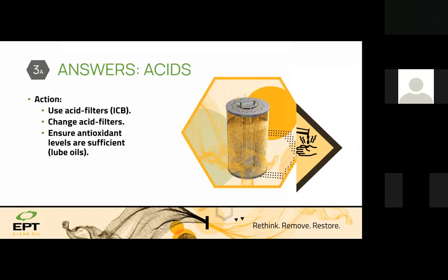And if you feel acidity is going high, the best filtration technique is to use acid filters. Ion exchange technology removes the acids in soluble form before the oil becomes saturated, and then you will find varnish in the system and so on. So it is better to install ion exchange filters from the start of filling the lubricants, removing acids from day one, not allowing the acids to combine and damage the lubricant more and more.